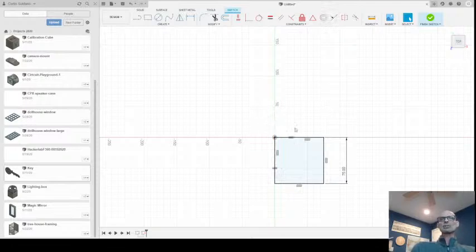Now I don't know if you noticed all the colors of this sketch have turned to black. You also notice that there is a small red padlock icon that appears next to the sketch item up in the browser. That tells you the sketch is now fully constrained, and that has significance in that if you accidentally enter a number differently, the attributes of your design will be retained.